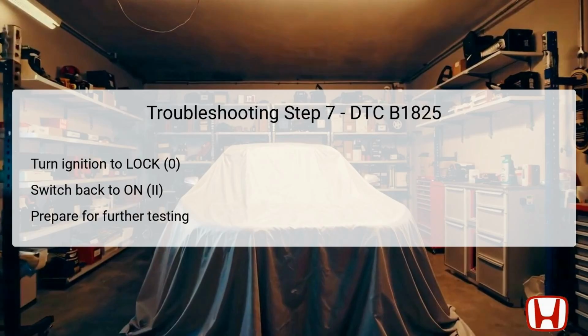Similar to previous steps, it's crucial that technicians accurately complete this action to eliminate erroneous results or failures during testing. The vehicle must maintain a stable power supply for the seat adjustment mechanism to function correctly. Once complete, the technician can proceed to operate the slide switch for further assessments of the motor's functionality.